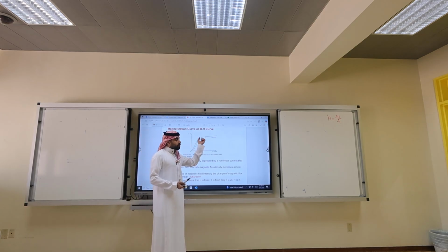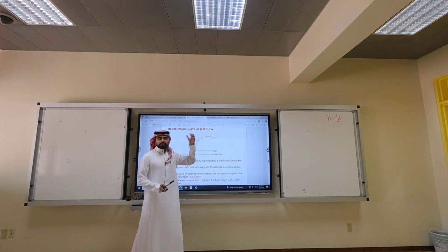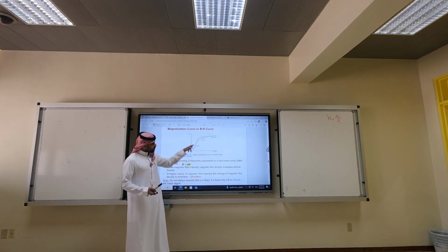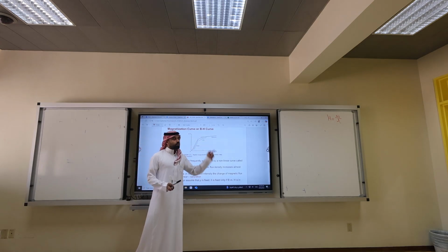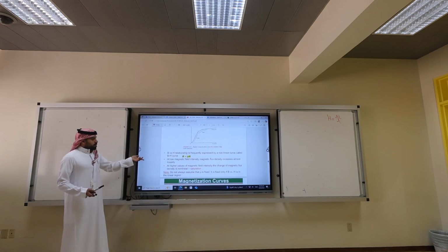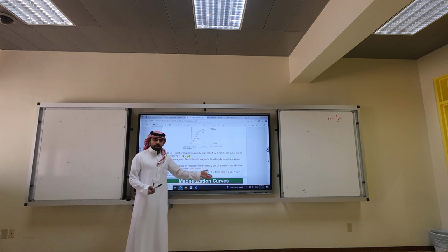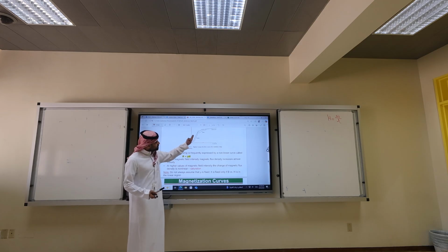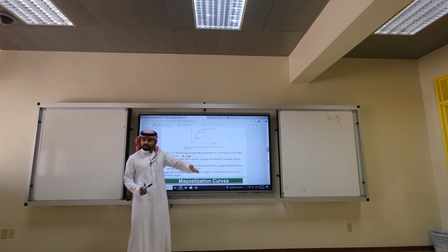Now, in a motor, if you want to slow down the motor, you can reduce the current, slow down the flux, slow down the speed, or increase it. Think of it that way. As long as you're in the linear region, it is okay. We don't want to go into saturation, because if you go into saturation, you might heat up, you might have irreversible damage. So do not always assume mu is fixed, because the slope, as you can see, changes. It's not 100% linear.